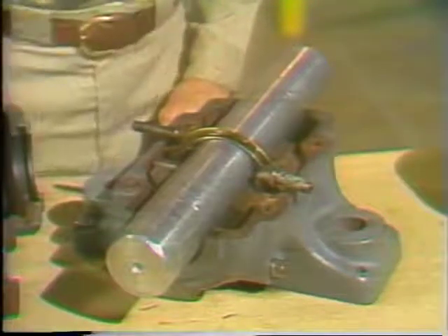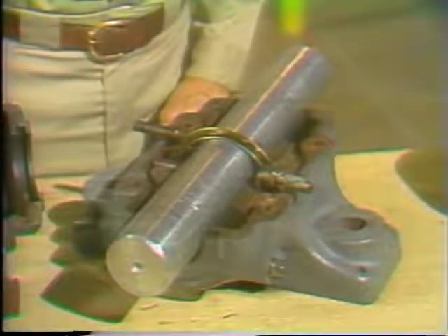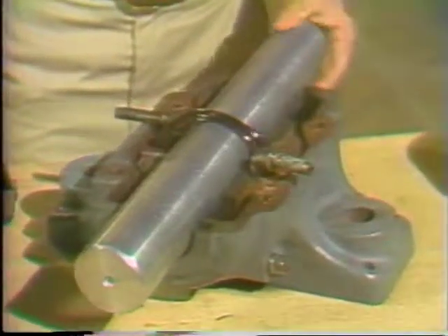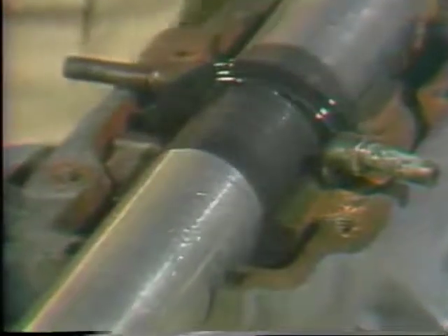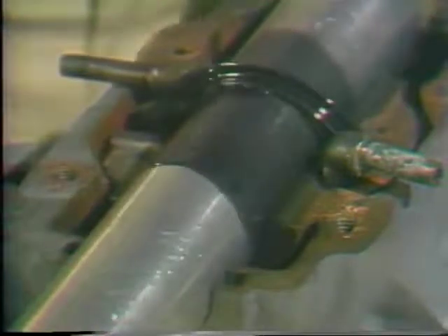The lubrication process is really quite simple. Half of the ring is always suspended in the oil reservoir. So, when the ring and shaft turn, oil sticks to the ring and is deposited onto the shaft during rotation. The oil then spreads throughout the bearing and proper lubrication is achieved, as you can see here. A continuous film of oil is supplied to the bearing and shaft by this method.